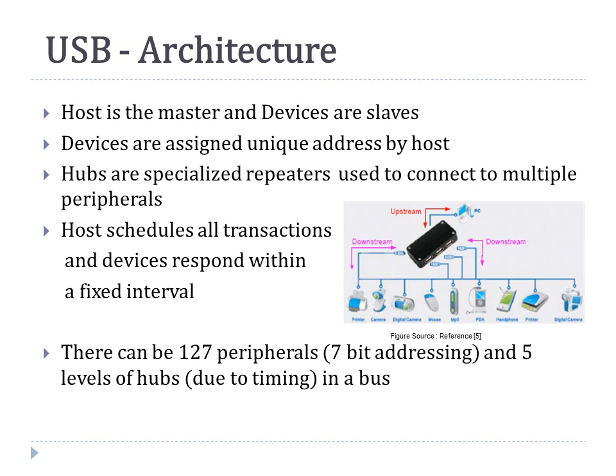the same bus. As mentioned, the host is the master of the bus and devices are slaves, and each device is assigned a unique address by the host. And whenever it receives any data which is broadcast in the USB bus addressed to it, the device responds to that request. It should be noted here that USB 2.0 is a half duplex bus, where both the transmit and receive happens on the same wires.